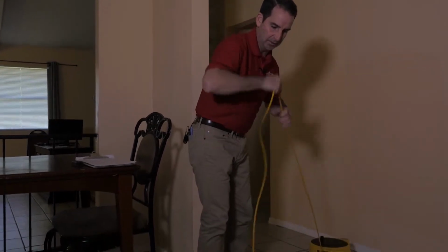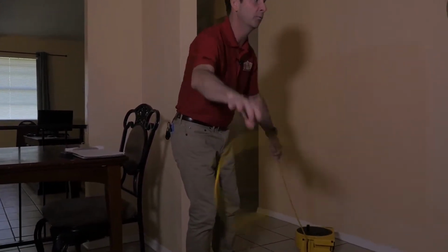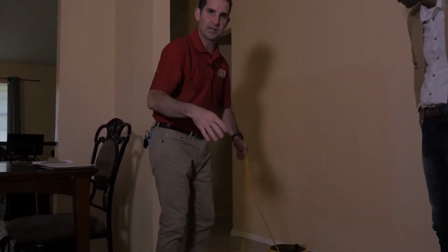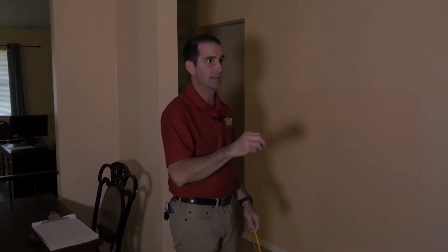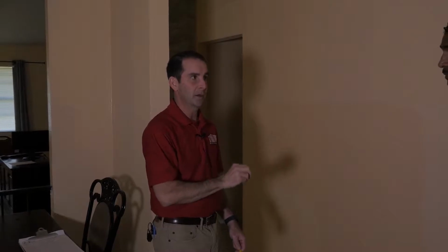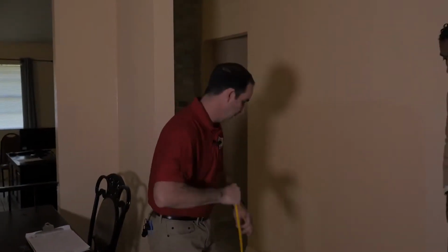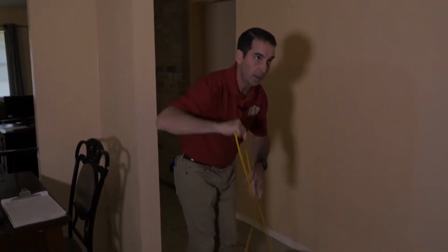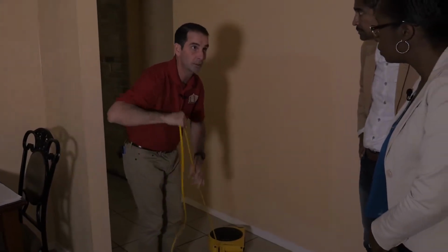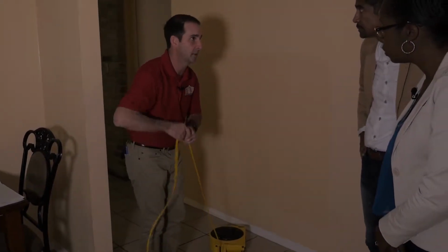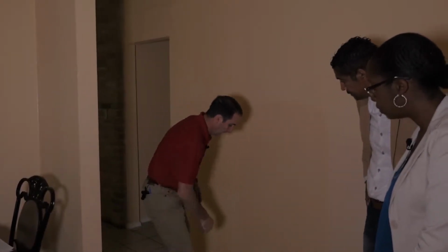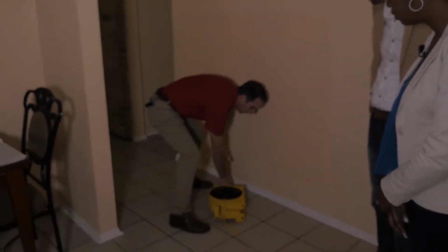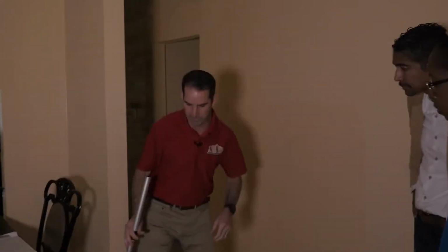So what I'm gonna do is take this meter and pick a reference point, okay? That means a point where I'm gonna set the meter to 0, so that every measurement that I take from there is going to be relative to that reference spot. Now the reference spot is an arbitrary spot. It could be anywhere. It could be on the street, it could be on the roof, but that's not very easy for me to do. So I'm gonna do it towards the middle of the house because it's easier to explain to a homeowner what's going on with their elevations.